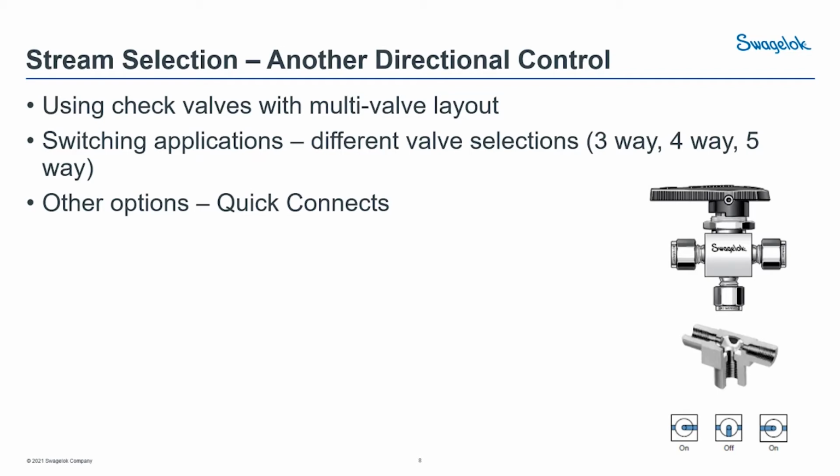So first here is a 3-way valve. You have a common port where the fluid comes in, and then you can switch by turning the handle to either go one direction or the other. And this shows the porting configuration down below. So this is very nice if you're trying to control fluid flow and you're trying to select between one fluid or another, or one direction or another for the main inlet fluid.